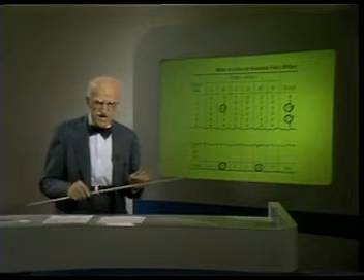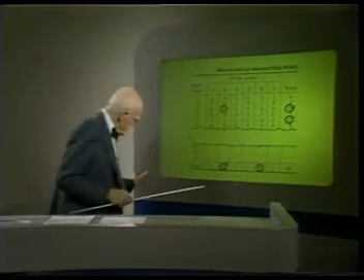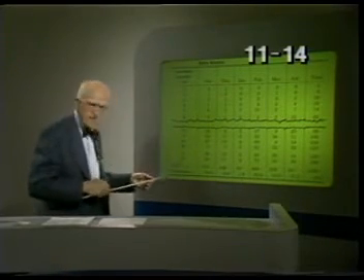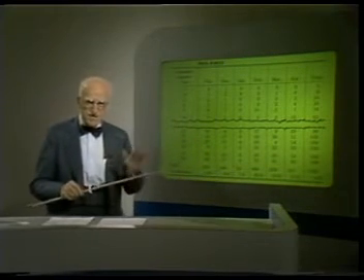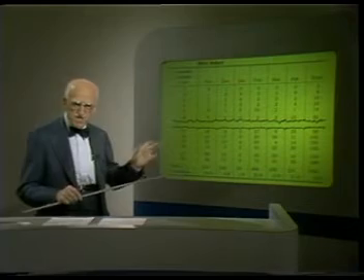Another matrix form combines dissection by workers with test of time-to-time consistency. The matrix for the gun assembly case shows the workers in one direction and time, month to month, in the other direction. It conclusively proved that some workers consistently had 10 times as many defects as others.